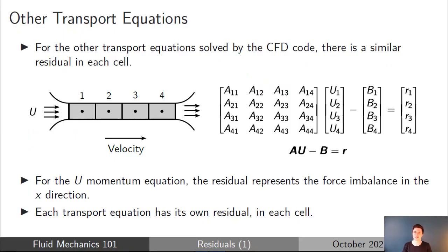Now, I also wanted to mention that throughout this talk I've been framing things in terms of the energy equation, but of course the CFD code goes ahead and solves other transport equations as well. CFD code will solve equations for momentum, so u velocity, v velocity, w velocity. If you have a turbulent flow, it will solve for turbulent kinetic energy, for example, and some scale determining equation. And if you have multi-phase or multi-species flows, you will also be solving other equations for those particular quantities.